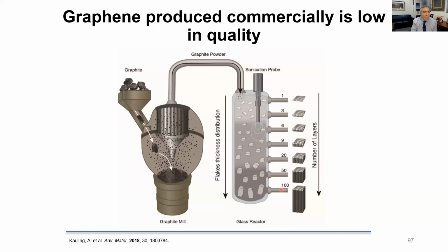All right, graphene in bulk. So that's graphene on a surface. If you're going to do graphene in bulk, this is how it's produced commercially. You grind up graphite, and it goes into this grinder. And then when it's small enough to get through this filter, it goes on through. And then the smaller ones come out the top. These are called graphite nanoplatelets. The bigger ones go toward the bottom. The biggest producer in this method is XG Sciences, came out of Michigan State. They're making about 6 tons a year. Everything they make is purchased.